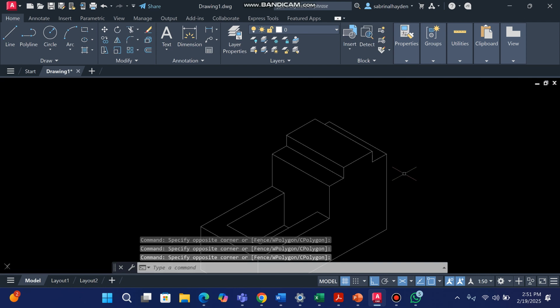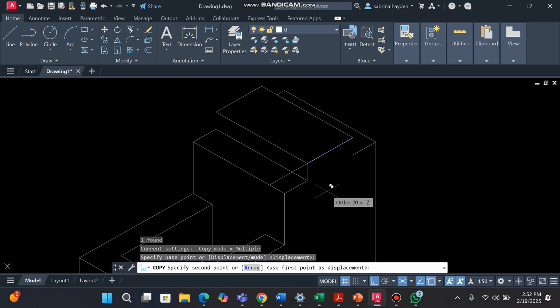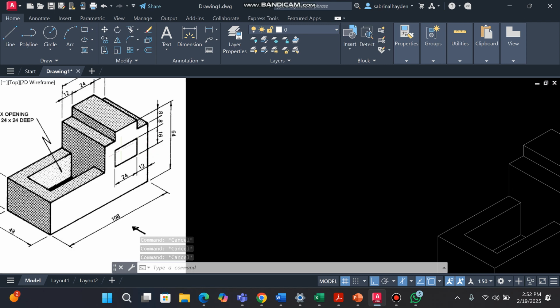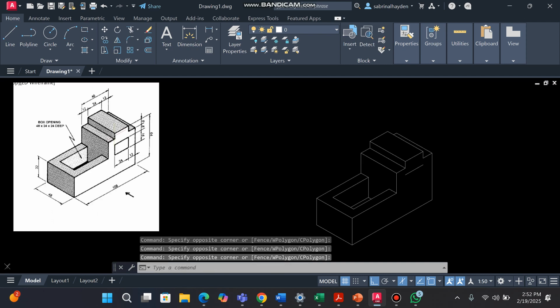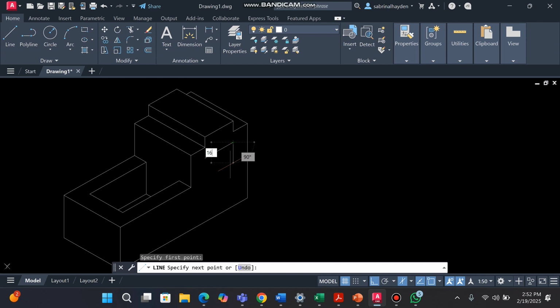All right, so copy, going down, you can change the orientation. Right, so going down, we're just going to type 16, enter. It's in position. Now, we need this to be 24, sorry, not 2.4, 24 millimeters. The face up here is already 24 millimeters, so we do not need to change the line that we just copied. What we must do now is go down 16 because that's what the measurement on the image said. The lines that are going down are 16 millimeters. Let me go back over and look.